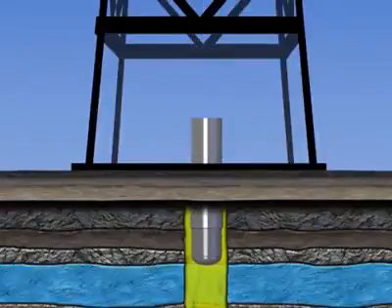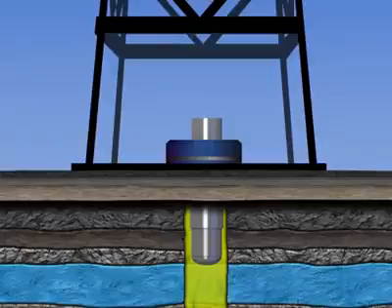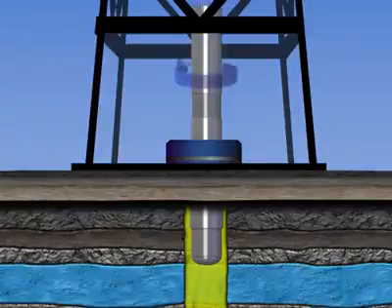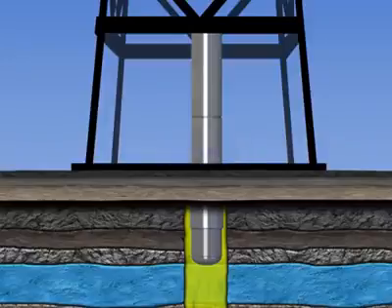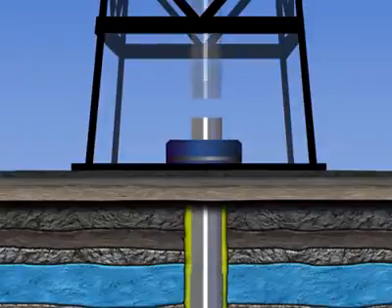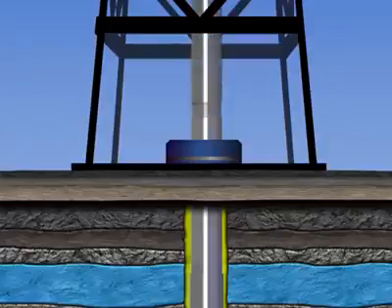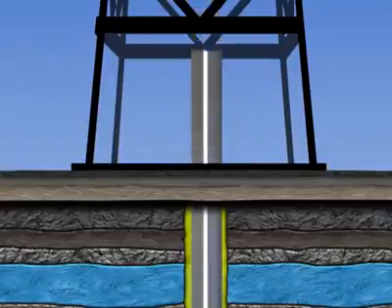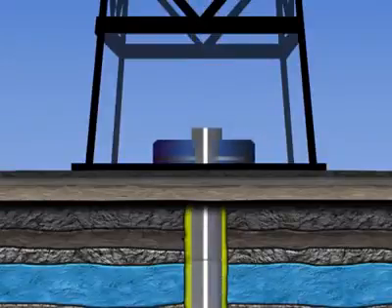The casing string is made of numerous joints the same size screwed together at the collar. The casing pipe is selected according to its outer diameter, its wall thickness, its length, its weight by unit length, and the grade of steel it is made of. The selection of grade of casing depends on several variables, including the size of the hole, the rugosity of the drilled hole, the expected pressure of the flowing hydrocarbons, the H2S content, as well as economic considerations.